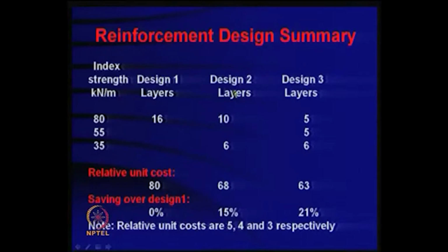The second configuration that we discussed, 10 into 6, it is 68, and for the third one, where you have all three things, you have 5, 6, 6, it is 63. Even within that geosynthetic material, see what you did, 80 meters is definitely unstable, you do not get any factor of safety, it is definitely less than 1, and you use geogrid reinforcement as reinforcement.